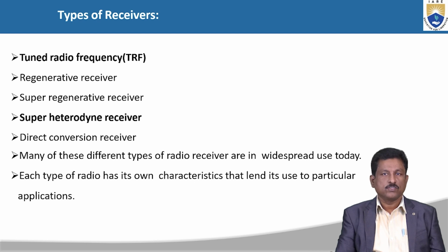Then there are regenerative receivers. Another one is the superheterodyne receiver. You know that. So what is the meaning of heterodyne? Mixing of two signals. Heterodyning means mixing two signals by the operation of addition or subtraction. We can generate the IF frequency, the intermediate frequency. That is the main purpose of the superheterodyne receiver. Even though our received signal is in the megahertz range, it can be converted to the IF value by the heterodyning operation, which may be an addition or subtraction operation.